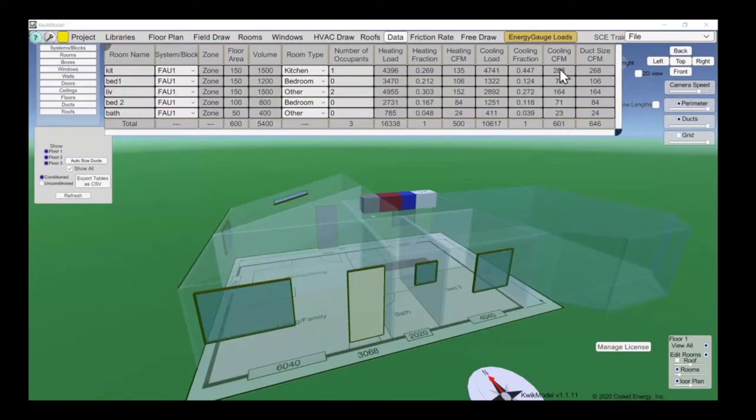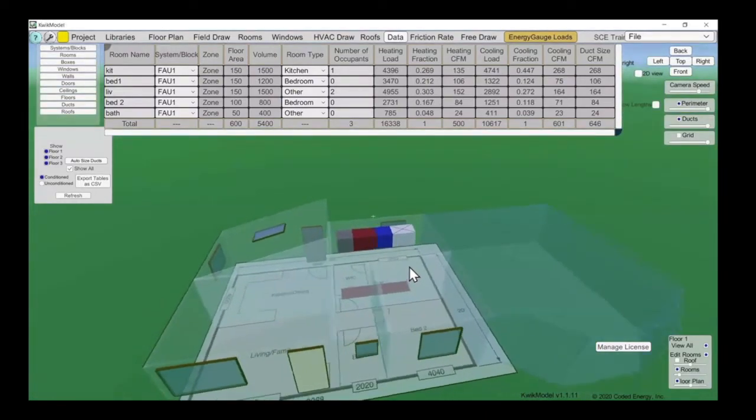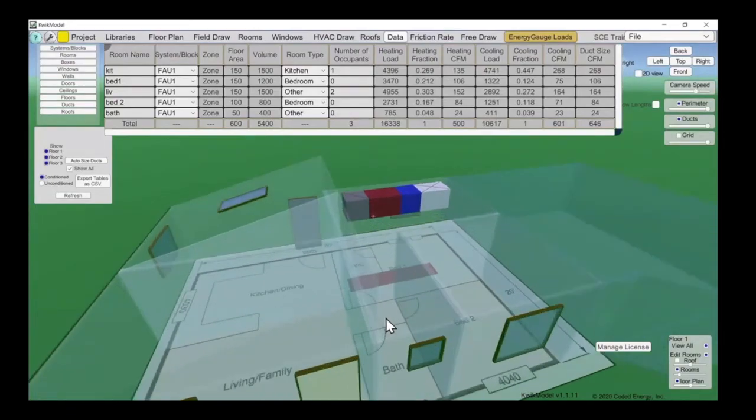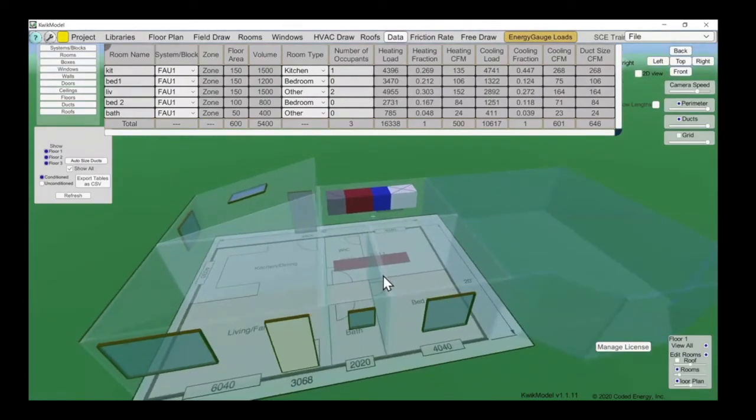So you can oversize the duct. The other thing, too, and this is just one of those nuances of duct design, is where are you going to put your thermostat? Because the thermostat is going to sense the air that's passing it, not the air in the rest of the house.